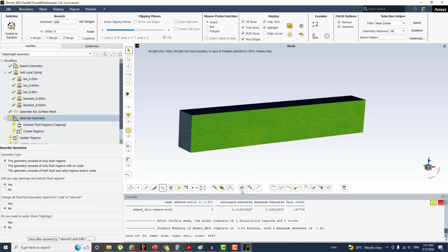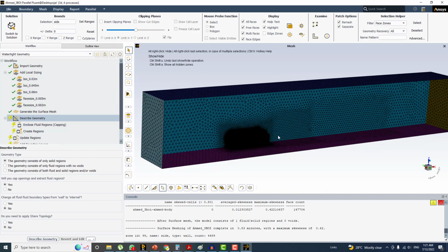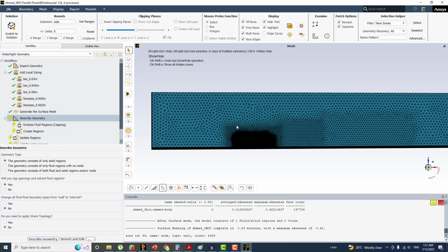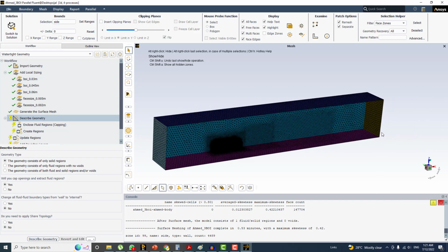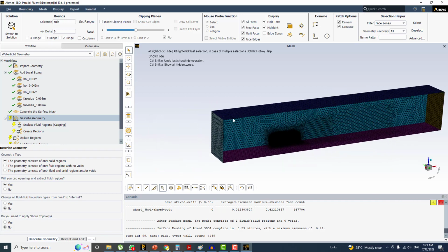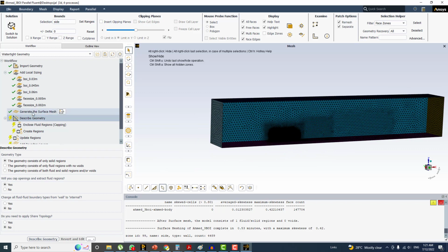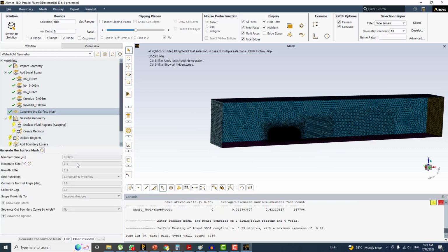Okay, now I can select this boundary and hide it from here, and you can see that we have the 3 zones of influence, or BOIs, bodies of influence. The one is around the body, second is the second wake region, third is over here, and then we have the maximum size element as we described earlier. And if you make the size maybe the default one, that is the 0.2.